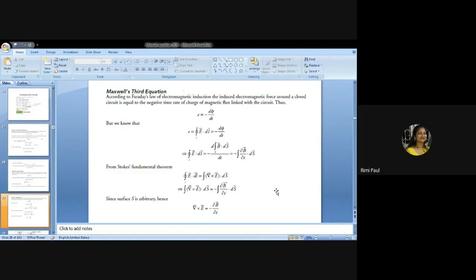Now, if I take a time varying field, that means when a wire, a conductor moves through a magnetic field by cutting its flux, a voltage is induced, because now the conductor is moving but the field is stationary. Now, if I take a stationary conductor and a varying magnetic field, that will cut the stationary conductor and it will induce EMF.